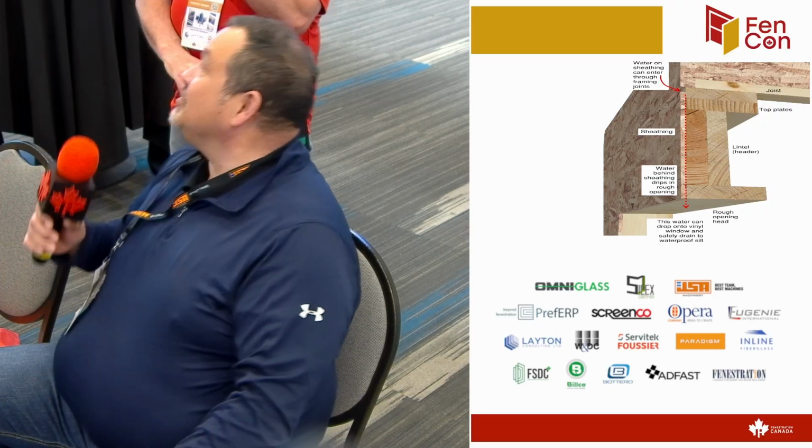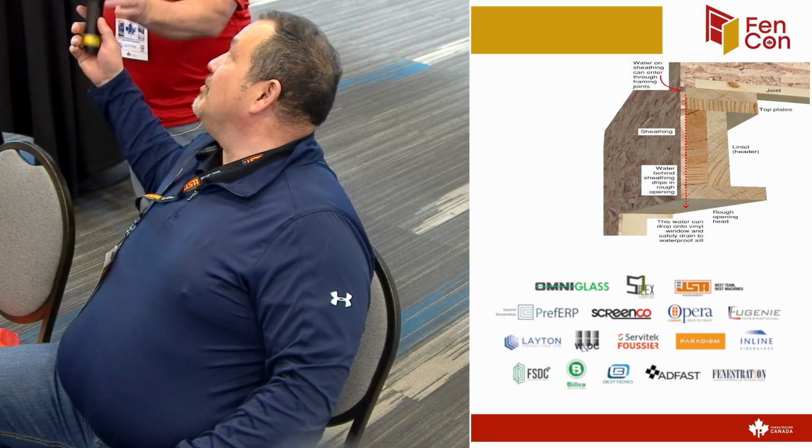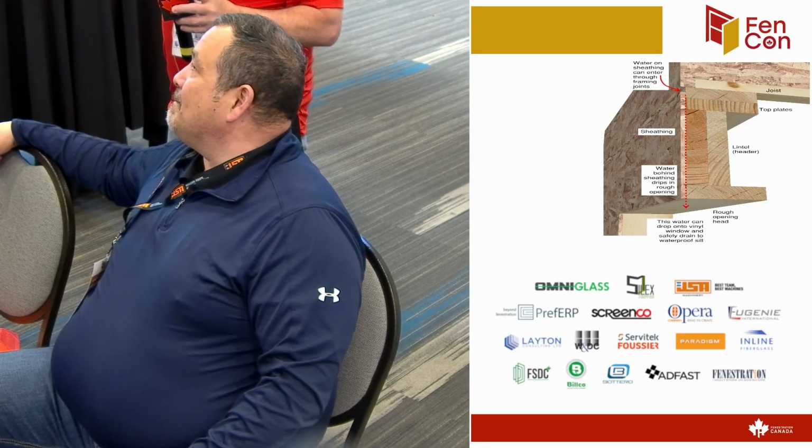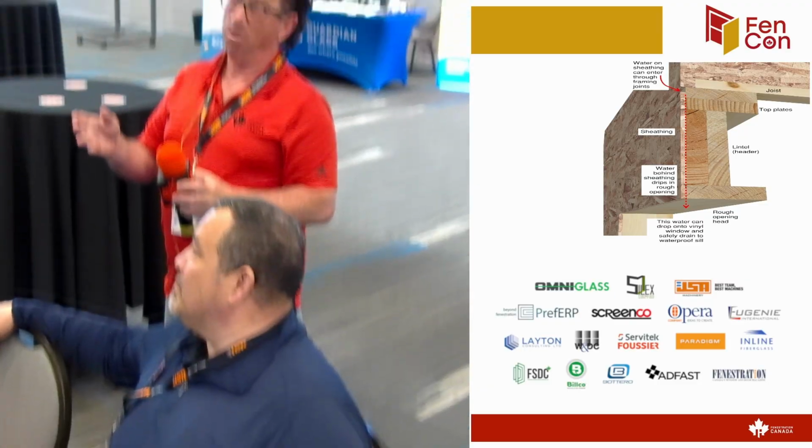How does that work? Is it thermal or is it air leakage that you fixed with insulation? I don't know. But I'm just saying, if it should only be half a degree or 1.5, either the whole thing should be frosting up, or it shouldn't matter if there was a pocket or not. But if you remove the casing and there's a void there, that's going to be an obvious air penetration as well. So it's probably coming from air movement, bringing that cold through. That would be my guess.